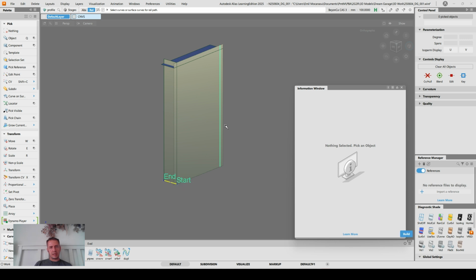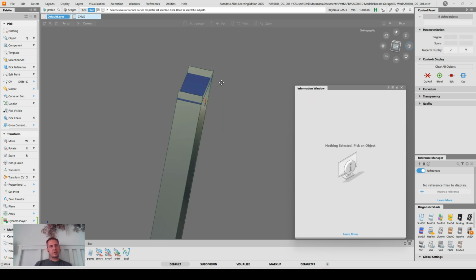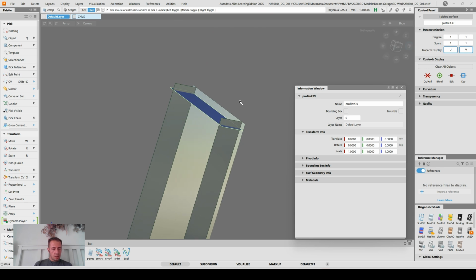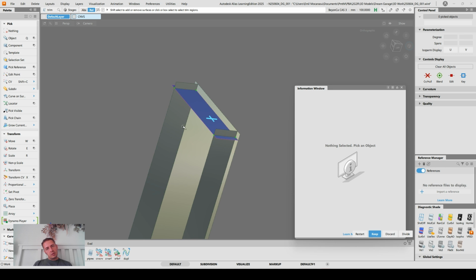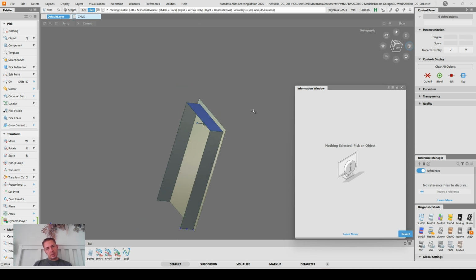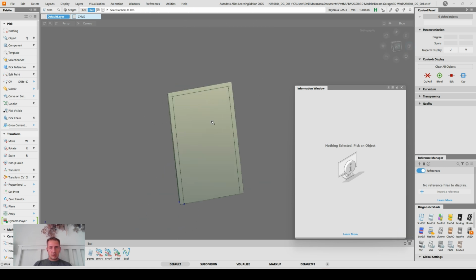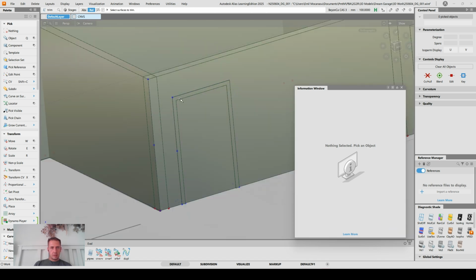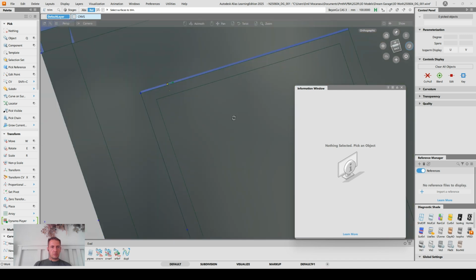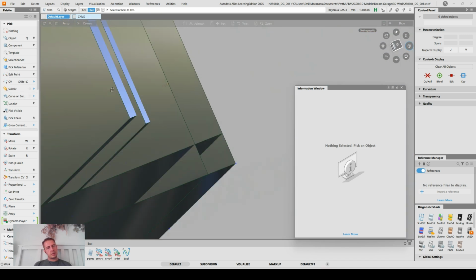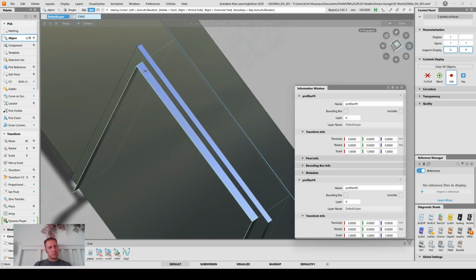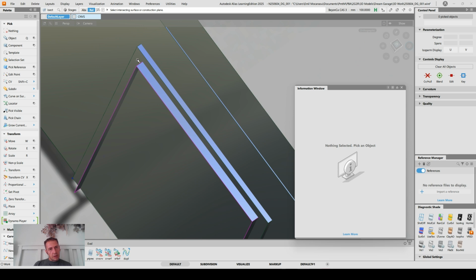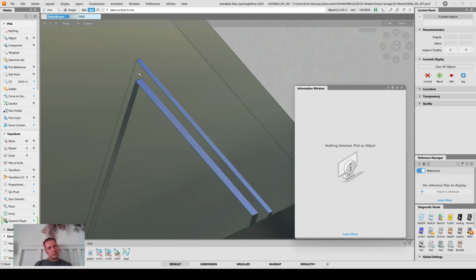I could have picked all the lines separately, but I don't want to do that because maybe for the fun of it, I'm gonna make a quirky door frame. So now what we will do is discard that in the middle there. And as you see, we've generated a nice door frame there. Now, let's take these surfaces. We will intersect them with the other side.